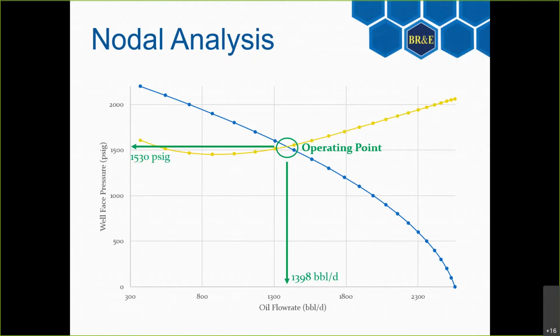And the beauty of the analysis here, and setting up these correlations and defining the curve, is that we can now change any property that helps set these curves up and figure out what the new operating point is going to be. Whether that's a future change to your production tubing, maybe you're going to change your tubing size, or maybe you're going to cut back on your choke valve setting and open that valve a little bit more. That's going to change the nature of the outflow curve. And then we can find the new operating point by just comparing these two together. So this now becomes a predictive way to figure out any changes in your system and how that's going to affect the production that you'll see.